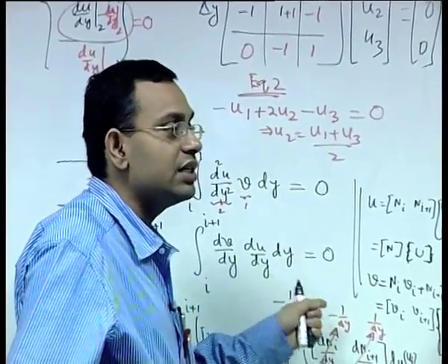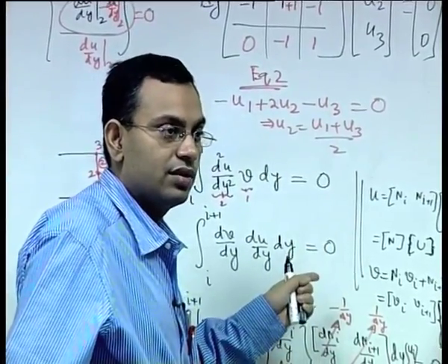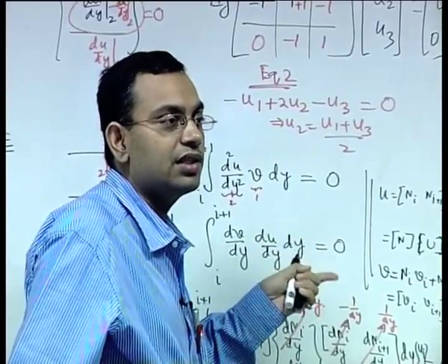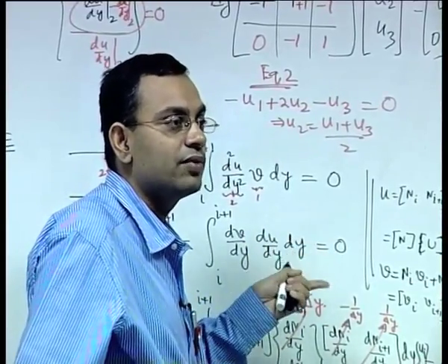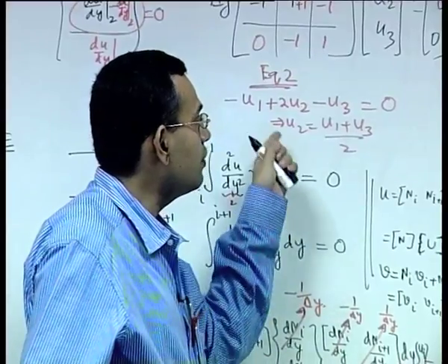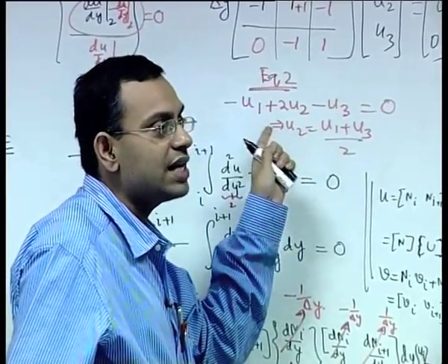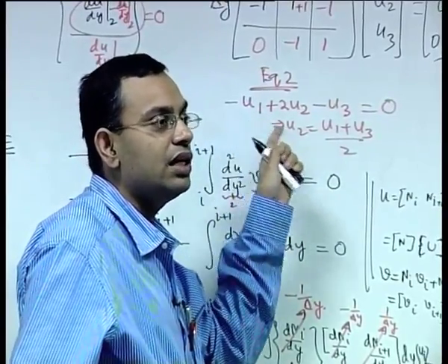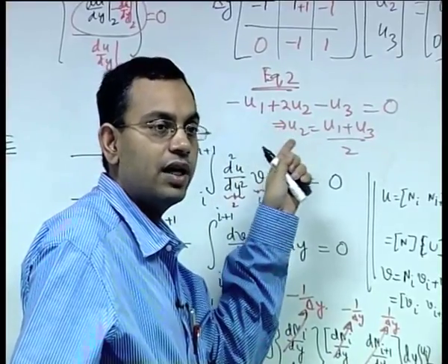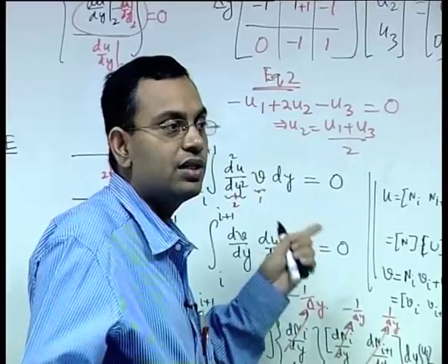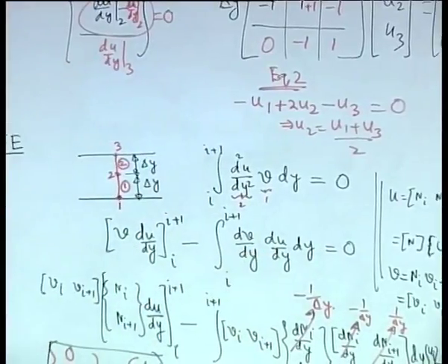And this is also not unexpected because here also you have considered a piecewise linear profile, which is the shape function or the interpolation function in the language of finite elements. So, because you have considered a linear profile, you will get the same consequence as that you get using a linear profile from a finite difference or a finite volume. It is a linear problem, so it does not have any scope of having any other variation.